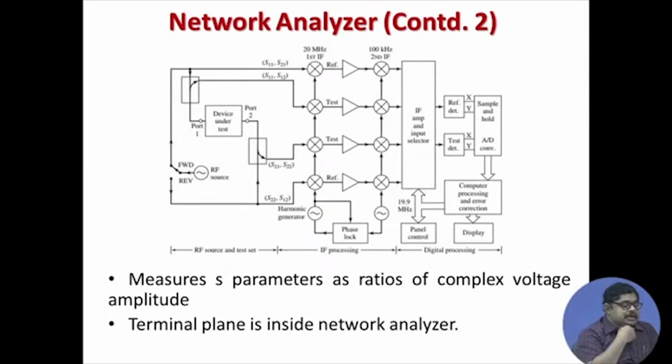It measures S parameters as ratios of complex voltage amplitude, that means it has a reference, with respect to which it calculates various ratios. Also remember this: suppose I directly measure some quantity, and the same quantity I take as a ratio with respect to some standard thing. Now, the ratioed measurement is always a better measurement.